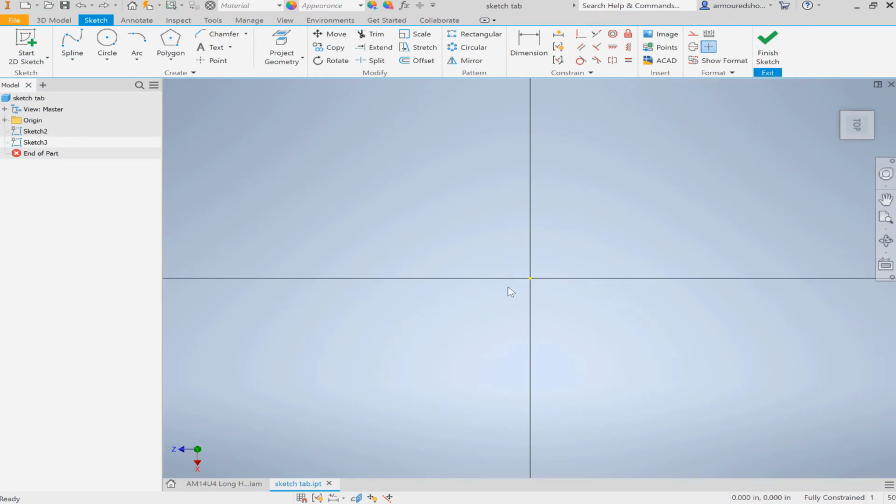so it freaks out. Okay, then next to this, we also have equation curve and bridge curve. Equation curve, you give an equation of the generated curve, and bridge curve will create a smooth line between two pre-existing curves. Next up, we have circle, which very intuitively allows you to create a circle.